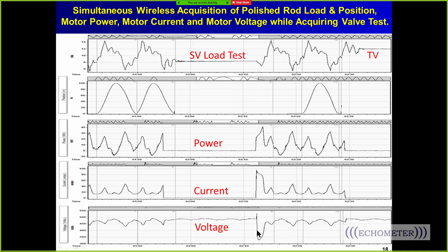And then when we turn it back on, you can see the drop in the voltage, because the voltage has to travel from the transformer to the well. It's like a pressure drop, voltage drop. And then the current jumps up to a really high value. That's called the breakaway current. And then the power starts out pushing hard, and it quickly pushes harder and harder until it breaks over right there. That's called the breakover kW, breakover torque. And then it starts to operate at normal speed during the strokes.